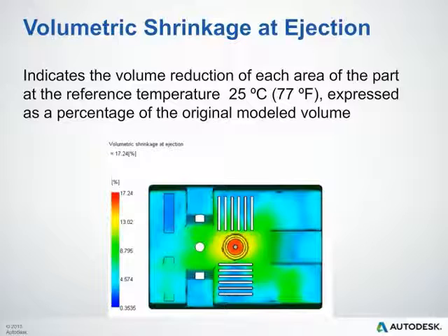To solve some of these problems, you can consider some of those pack profile tricks that we showed you in a couple slides prior. Because really, what we're trying to do is get a uniform shrinkage throughout the part, and some of those pack profile tricks could help there.